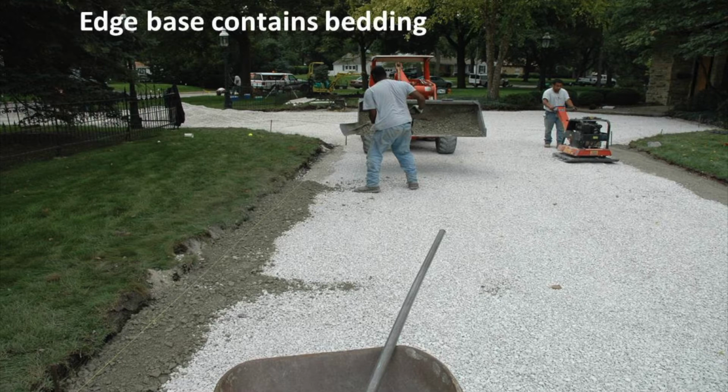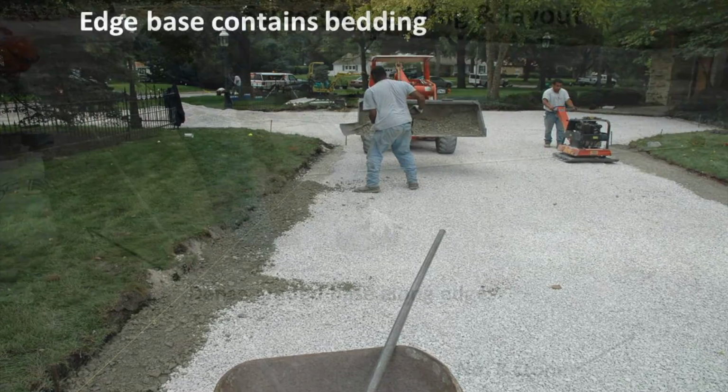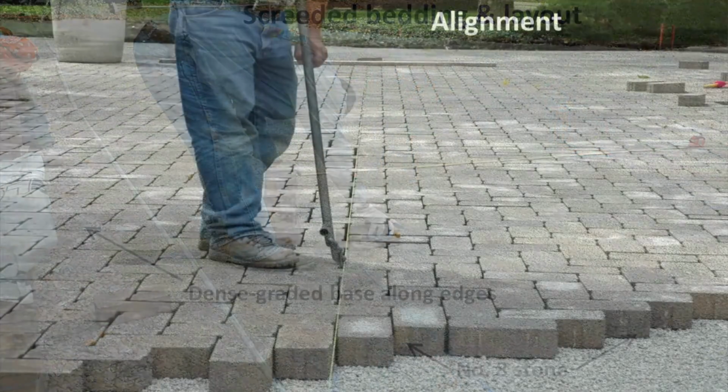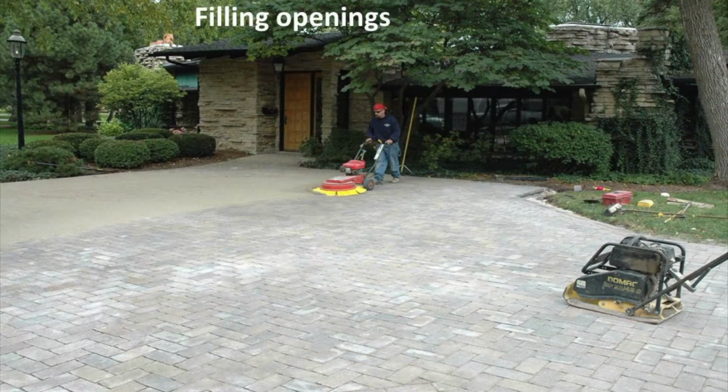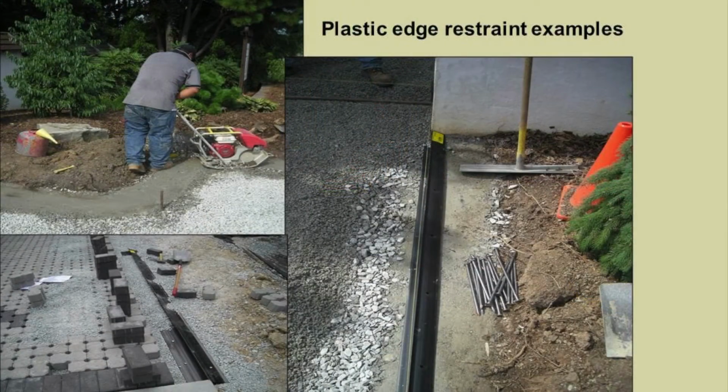If not, you'll have to have that taken out and done remedially. Then setting the pavers. Pavers are typically aligned and then compacted, and aggregate is swept into the joints, and that's how the plastic edge over that dense graded base is done. So in a residential application, you don't need to pour concrete. You can actually do a staked edging. You just have to use a typical dense graded road base instead of the open graded base.